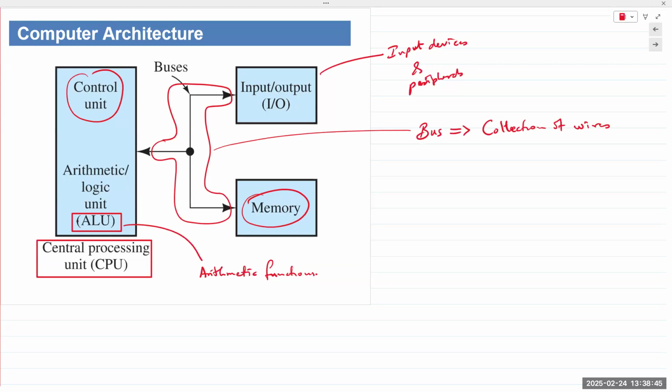Since all of the information is moving together on all those wires in parallel form, it's known as a bus. So remember, external peripherals can be connected via parallel or via serial connections, but internally, it's all parallel connections. If you have a 4-bit processor, you need 4 wires. It's a 4-bit bus, but you can only work with 4 bits at a time. And then you had 8-bit processors, you had 16-bit processors, then 32, and of course 64-bit processors are now the consumer grade standard, which require 64 wires to move data between the CPU and the associated circuitry.